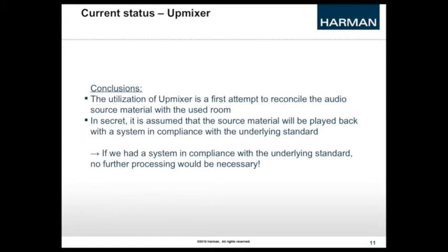So the conclusion is that the upmixer makes a first attempt to deal with the room and the speakers available in it. But as I said, it was assumed that the source material will be played back with a system in compliance with the underlying standard, which is not the case. Though if we had a system in compliance with the underlying standard, no further processing would be necessary.